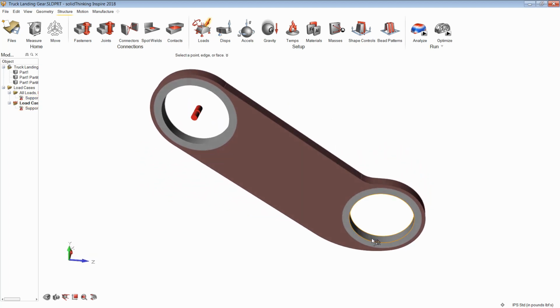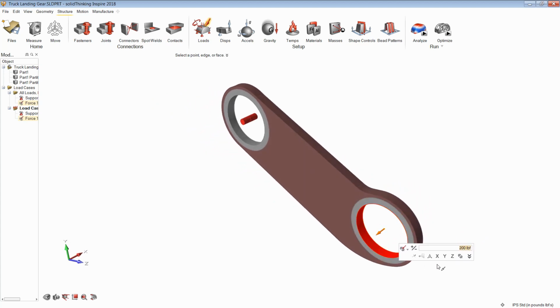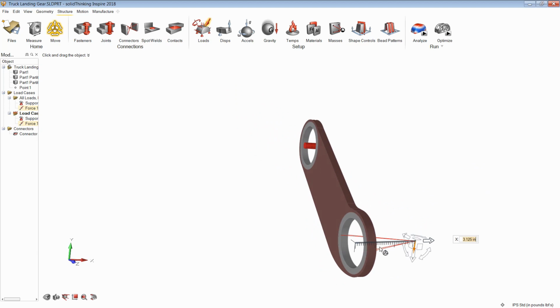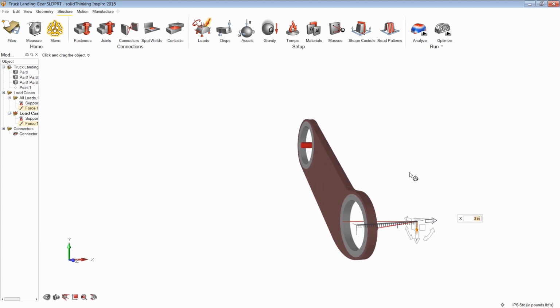So I'm going to add a load on this face, and I want it to be pointing downward, and imagine a 400-pound person stamping on this, so half the load is going to be 200 pounds. But the only difference is the load is not going to be on this region. So first off, direction of the loading is in the Y and negative. We're actually going to move this load away so that it's slightly away. So if the entire bracket leg space was about 6 inches, half of that would be 3 inches. So what this does is you're actually going to see a moment being generated on this structure because that load is offset by a certain amount. So you do have the option to offset that load to create a more realistic loading condition scenario. Okay, so that's that load.